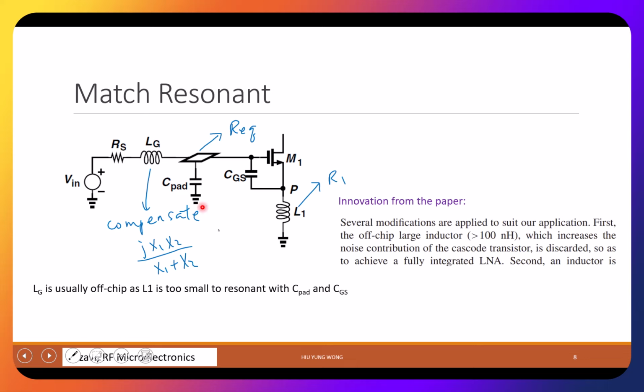Then the whole thing will become pure and real, right? So again, what is the strategy in all the circuit design? We come up with some idea using inductor or capacitor to form a complex input impedance, right? You have a Zin, which might be equal to real part plus jX. However complicated it is, we then adjust the element to make this 150 ohm.